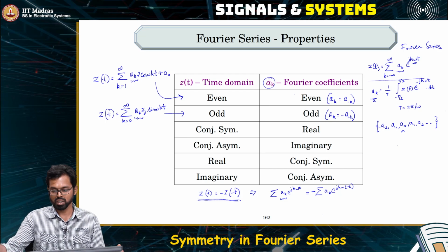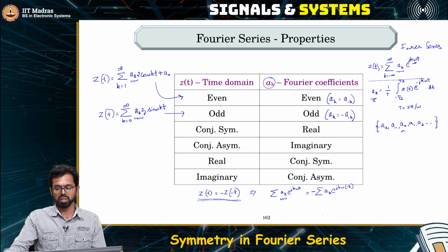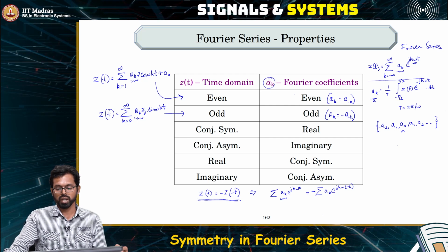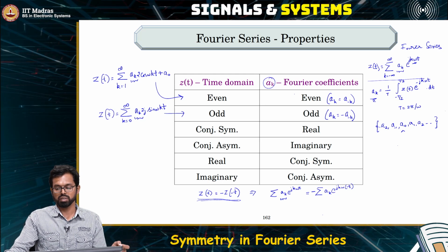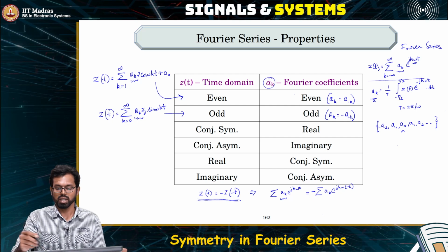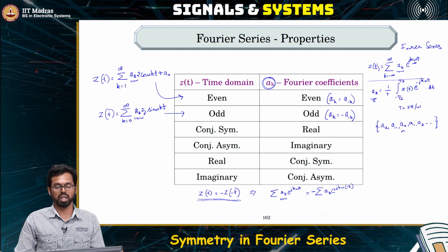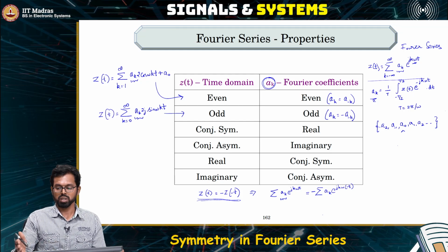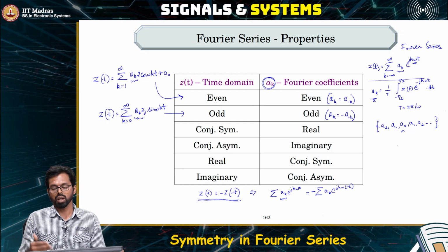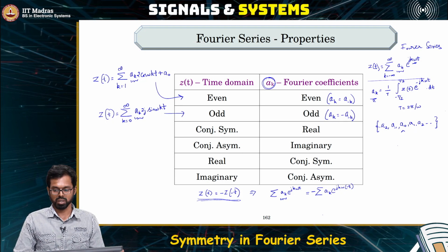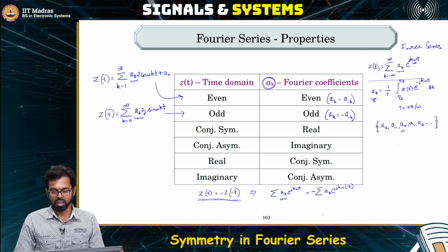That is, we have phasors on the right hand side which are different only in their frequency. So the way that we are denoting the different signals on the right hand side is by denoting their different frequencies and the magnitude with which they are added together. So the components on the right hand side denote the magnitude of different frequencies, or different phases, that are present in the signal that we have.